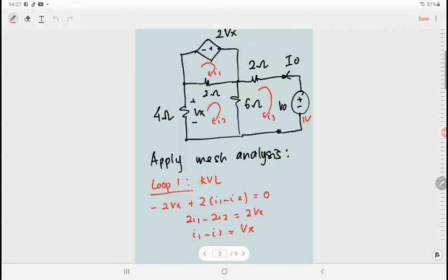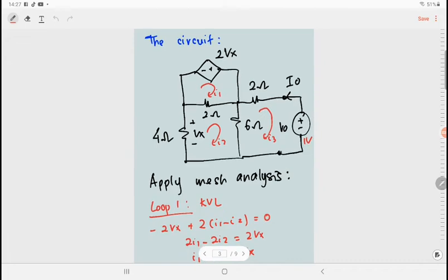Next, this is the circuit. Now we introduce V0 over here at terminal AB, a 1 volt voltage source. Our I0 is the current that we get from the voltage source that we introduce. So this is your I0. Our aim for this circuit is to find the value of I0, and from there we can calculate the value of RTH, which is V0 divided by I0.